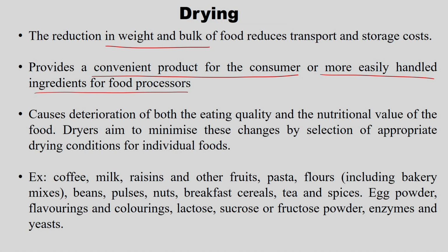It causes deterioration of both the eating quality and the nutritional value of the food. Since we are applying a thermal process done by hot air at a particular temperature, it may cause deterioration of the eating quality and the nutritional value. Dryers aim to minimize these changes by selection of appropriate drying conditions for the individual food. This is in our hands. If you remember our earlier classes, we also talked about the time temperature combination.